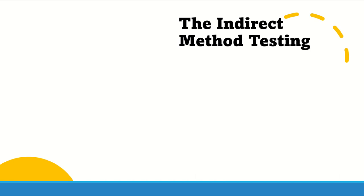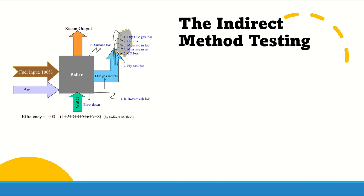In the indirect method, we calculate the various losses. See the diagram. Fuel plus air is supplied to the boiler, and water is supplied to the boiler, and steam is output from the boiler. It's the same in the indirect method. The difference is that we classify and separate each and every loss.